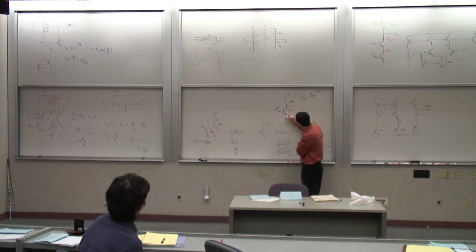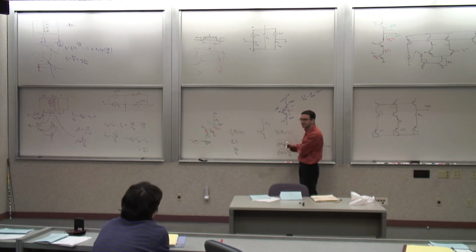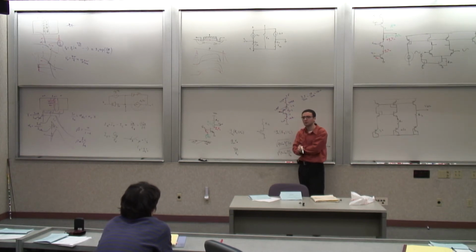And what is this current? This is 1 volt, this is 1K. It's still the same, 1 milliamp. This is 38 microamps. So, is this consistent? Yes, it is consistent, because this junction is forward biased now. This is carrying a lot of current through here that goes back in here. Your base current is now huge. You have a reasonably large base current because it's forward biased.